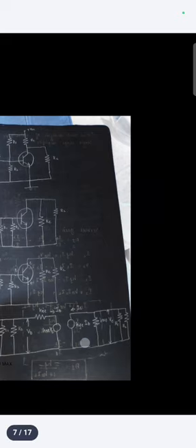Finally, we combined all the input resistors R1 and R2. Next one, H model. Using the H model, we use the common emitter H model. We already discussed how to draw the common emitter H model, isn't it? So employ that H model instead of the transistor symbol. Remaining all the resistors are connected as it is.